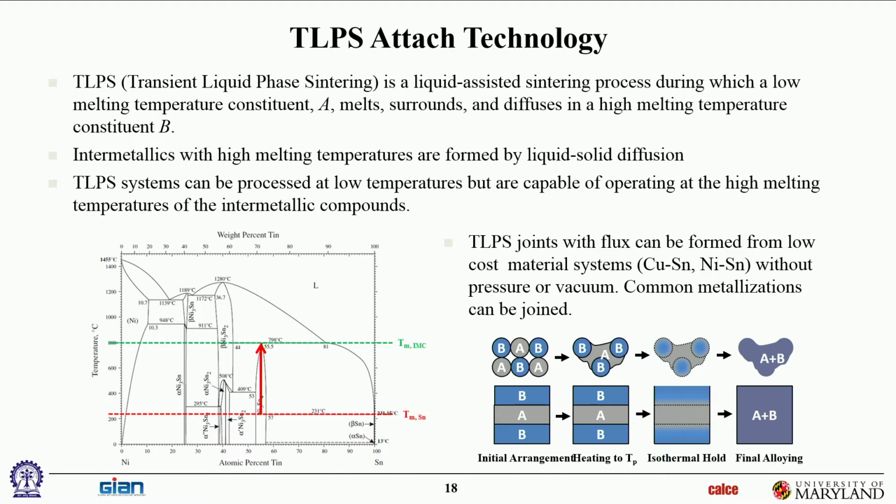They're still not, maybe the mechanical durability won't be as good as, for temperature cycling, they're excellent. But for mechanical shock, drop, and vibration, they won't be as good as more ductile die attach, but good enough for most customers' requirements is what we're finding.